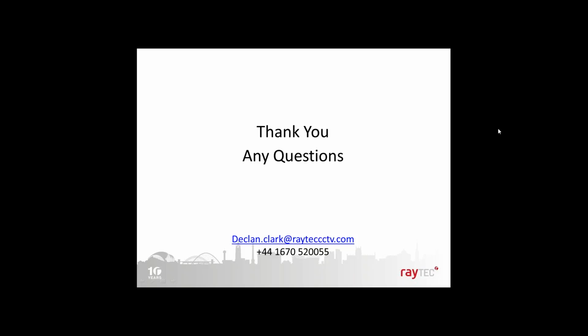There's obviously no specified standard at 50 watts yet, but it will work with certain mid-spans and injectors. But always speak to Raytec first about that, and we can recommend certain models that we know work with our higher power PoE units. I think it's PoE plus plus or super PoE or whatever they're calling it at 50 watts now.